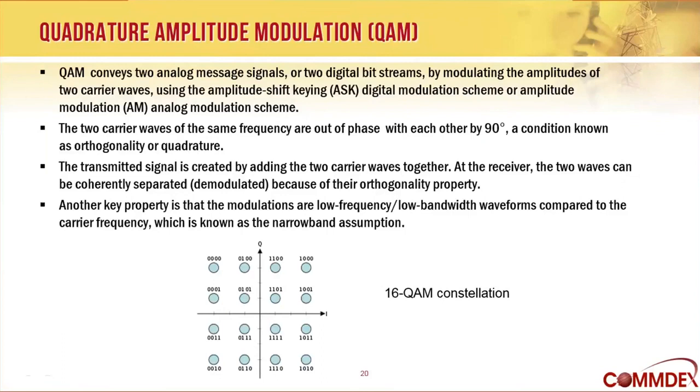Okay. So it gets really complex when you're talking about different modulations and you get into the phase diagrams and the constellations. But the main takeaway about modulation is that there are many different ways to carry information digitally by varying the RF carrier using one of its components, its phase, its amplitude, or its frequency, or some combination of the above. And there are 100 different ways to modulate a signal digitally, and we covered a few of the ones that are most commonly used.